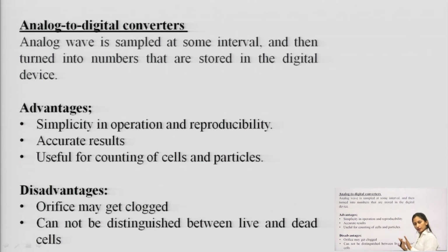So, here in this lecture we have studied two methods for the determination of powder particle size. One is the sedimentation method and the second one is the Coulter counter method. Coulter counter method is basically used for the particle volume determination, and sedimentation method by using Anderson pipette for the determination of the powder particle size by the weight distribution methods.